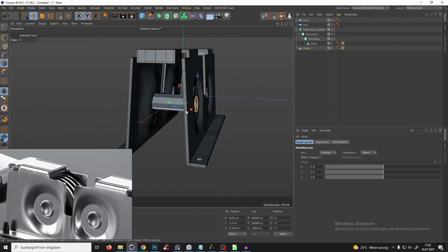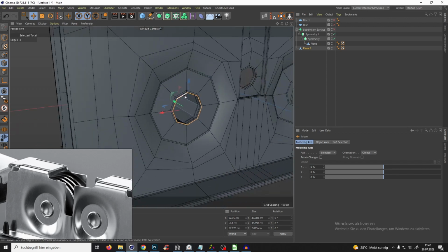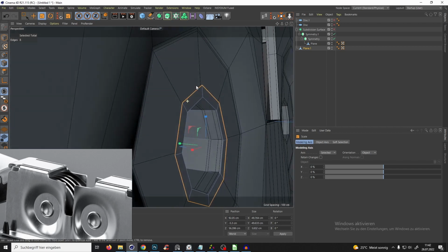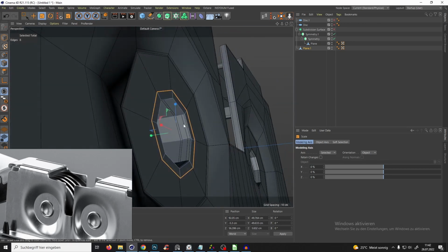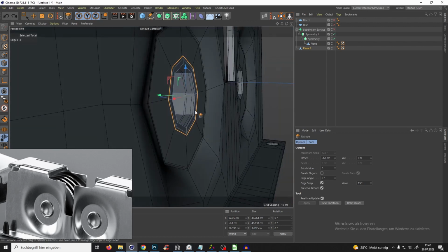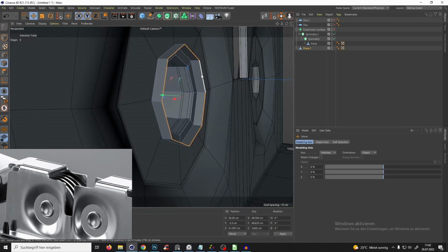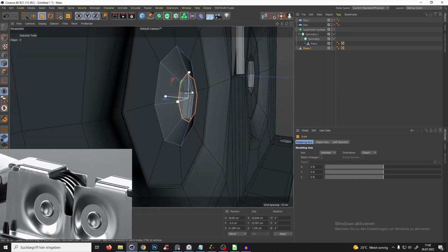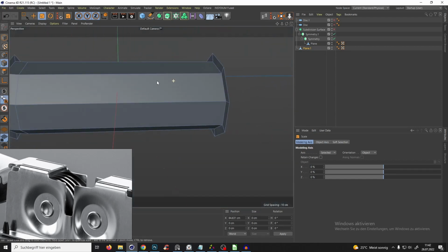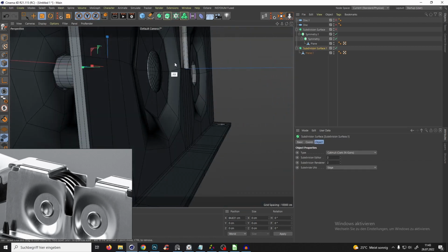So yeah, we have something like that. And how does it look on the original one? Ah, yes. Now what we can do again is bring this a little bit more inside, and T for extrude, and make it bigger. And in the original one, we can just make D for extrude. Oh, it's not working that way. So we select our outer edges and bring them down a little bit with control click, scale them a little bit down and right click and collapse. So you see we have kind of a nail or something. And if we give it a subdivision, we